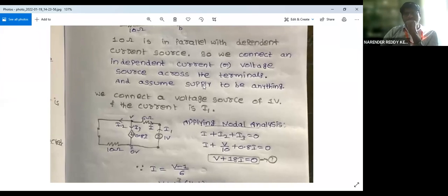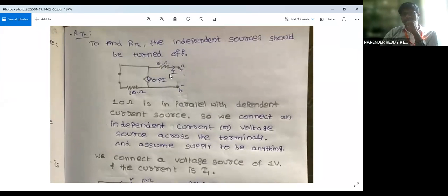Okay. So what we have to do, in yesterday's assumption, if we assume this to be a current source, and since I replace the voltage source with a short circuit here, what should I do with the current source? I should open circuit this, right? So the equivalent resistance could be directly given as 6 plus 10, that is in series here. But the problem here is that according to the statement of Thevenin's theorem, the dependent sources have to remain in the circuit and cannot be changed while finding the value of RTH.